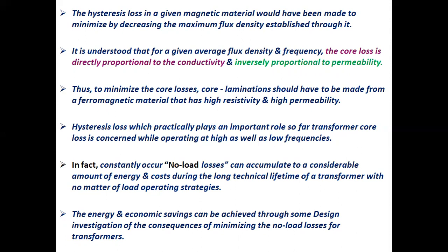Thus, to minimize the core losses, core laminations should be made from a ferromagnetic material that has high resistivity and high permeability.